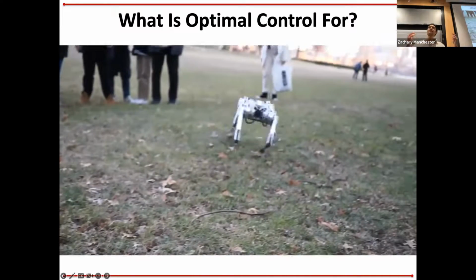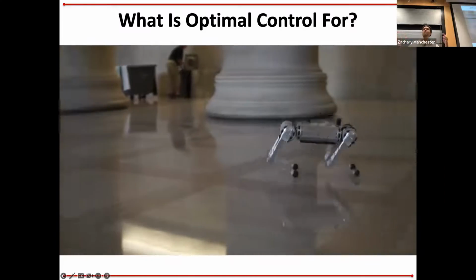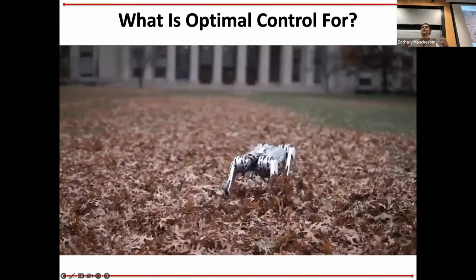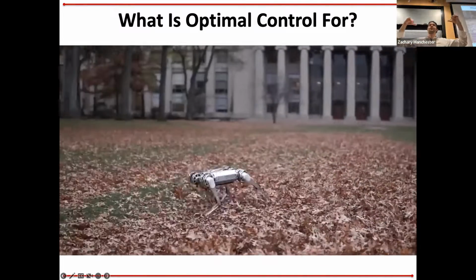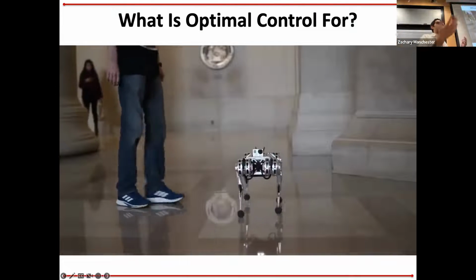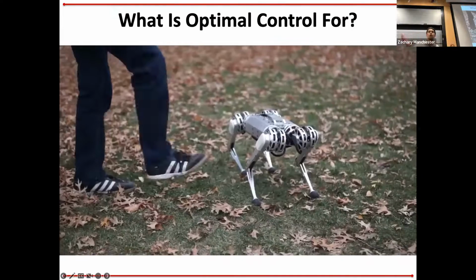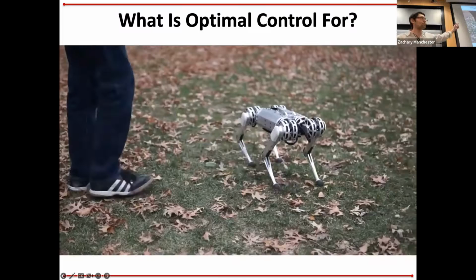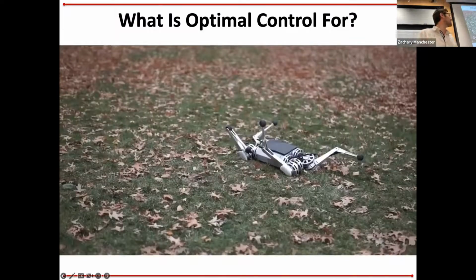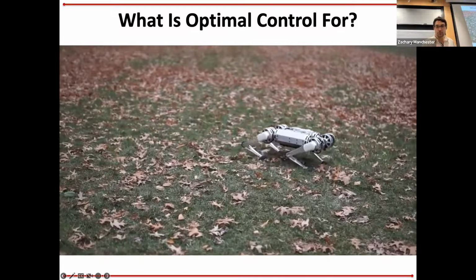You do some fun tricks where you essentially assume the legs are massless, which is a reasonable approximation for these robots, actually, because all the motors are in the body. So the legs are only maybe 10% of the body mass. Then you can get that MPC problem to solve at hundreds of hertz online. And then you can do fun kick-the-robot demos that mostly work. So pretty much all that legged stuff is doing this too.